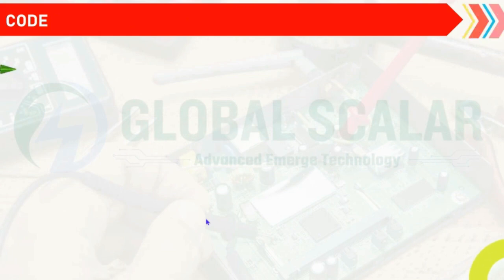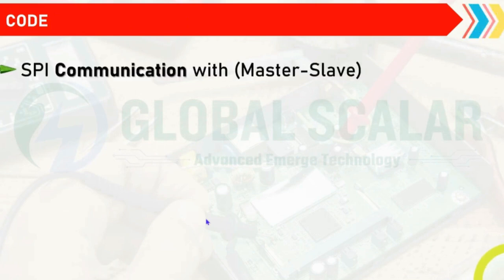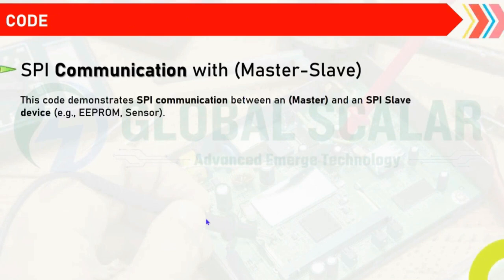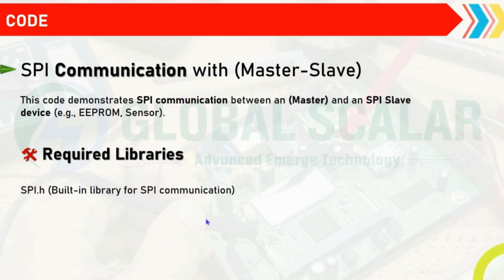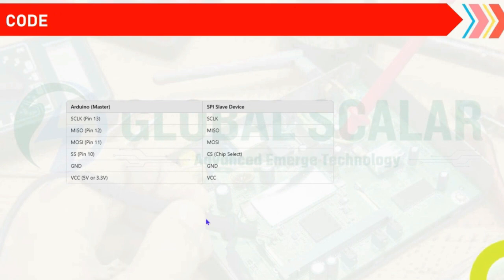To configure with respect to the code, let's see how the program looks. We need to understand the initial phase of the master and communication. The code demonstrates SPI communication between the master and the SPI slave, which here is the EEPROM or any sensor. Generally some of the tools have inbuilt libraries, so we require the initial libraries, and we need to understand the pins. Here we chose the pin configuration of pins 13, 12, 11 and 10, common ground, and 5 volts to 3. So we chose 6 pins for transferring our data, like clock, MISO and others.